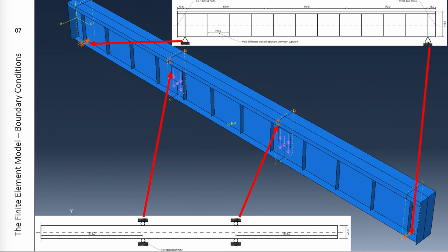When applying the boundary conditions as shown, there was a small discrepancy for the lateral restraints. They did not act over the full height, but just at the lips. This meant initial calculations overestimated the twisting resistance, meaning LTB, or lateral torsional buckling, was more critical.